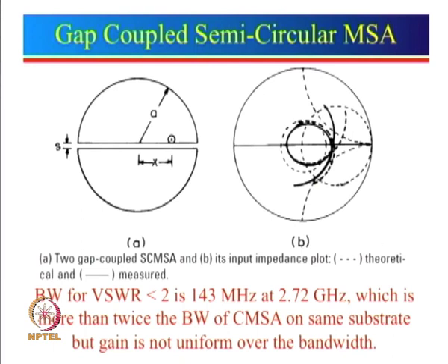Similar to that, we have also repeated something which I mentioned about the equilateral triangle in the last lecture. So, the equilateral triangle and the 30, 60, 90 degree triangle both have the same resonance frequency. So, they can also be coupled, and one can get a broader resonance frequency. Now, similar to rectangle or circle, one can also put triangular patches which are gap coupled, and you can still get a larger bandwidth or gain. So, their effects are very similar.